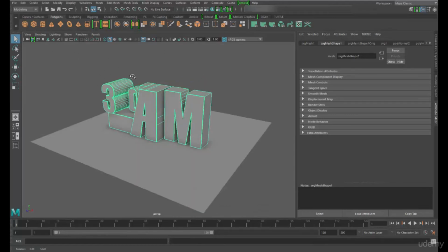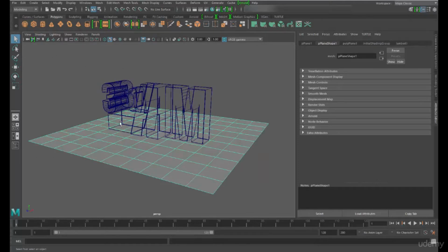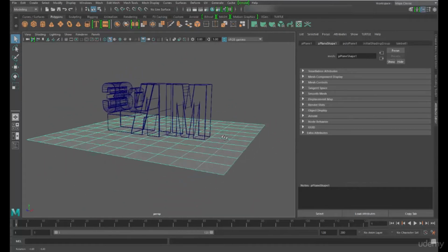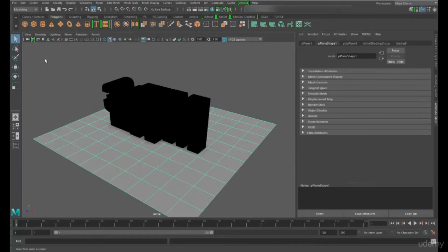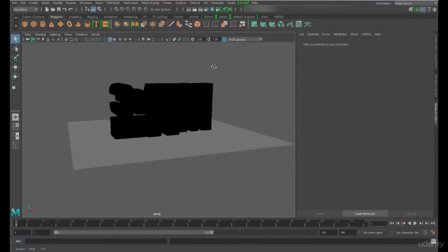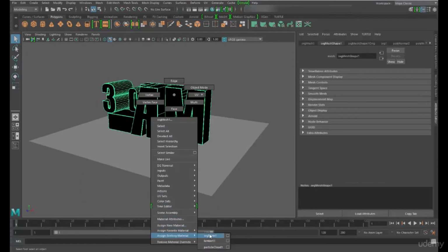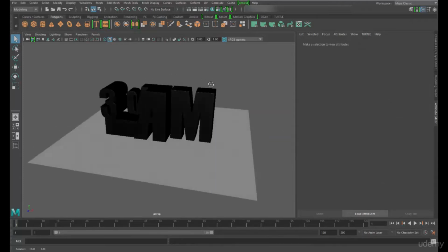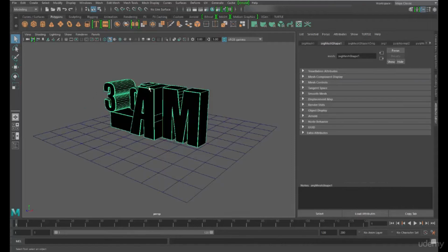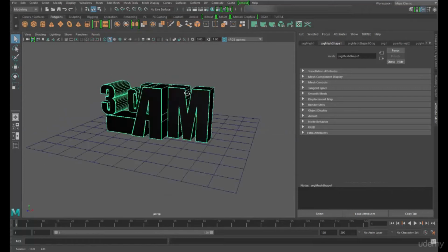Then if we walk through some of the options that we have for the shading, we can see that we can do shading on selected only. This is quite useful when you're trying to isolate or just look at what the ground plane's looking like. We have flat shade, so this is going to take away, let's just turn off the ambient, any of the shading going on inside the model. Let's put the blend shader back on, that's that one. Then we have a flat shade on selected items, very similar. So you see when flat shading we're just picking up the light from where the default lighting is.